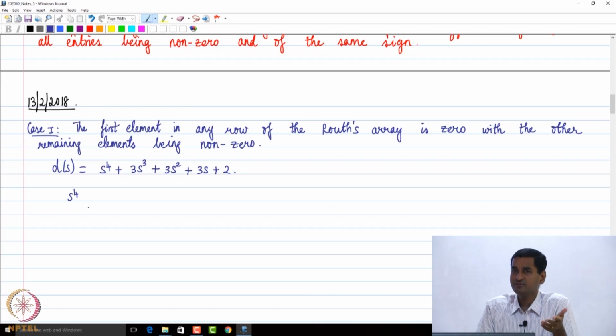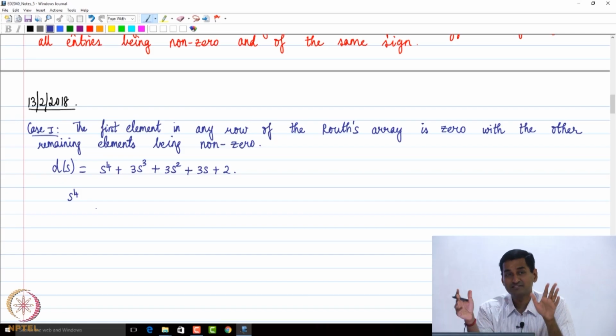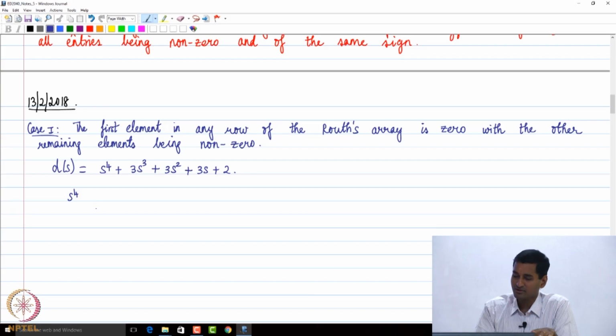If you want to figure out the distribution of roots, you can continue even if that necessary condition is not satisfied. That is the necessary condition for stability once you look at the closed loop characteristic polynomial. But in general, Routh's criteria can be used to figure out the distribution of roots of a given polynomial, so you can continue even if some entries are negative to see how the polynomial's roots are distributed. Anyway, let's continue and construct the Routh's array.